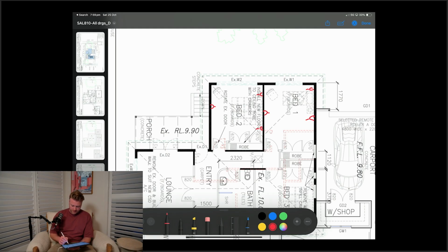With downlights, we've got a robe here, so normally I'd do a twin spot there. Probably have some art on this wall, so we'll probably put some twins here. And then we'd probably go for bedside, so one there, one there. These ones here, it depends. You can do these ones here or not. But yeah, nice and close to the wall.